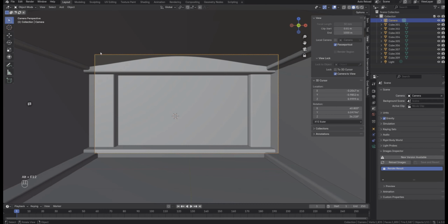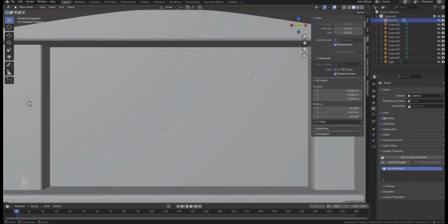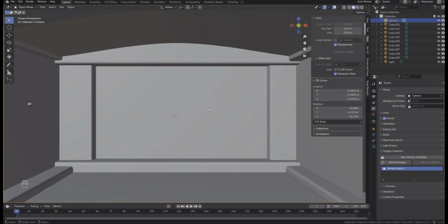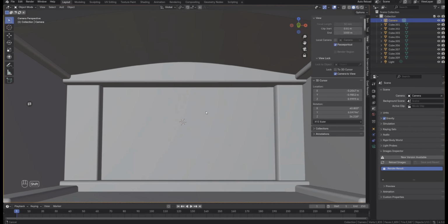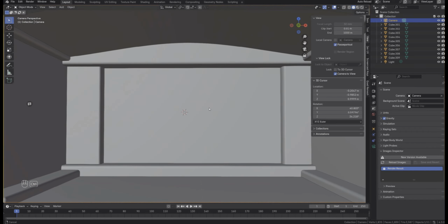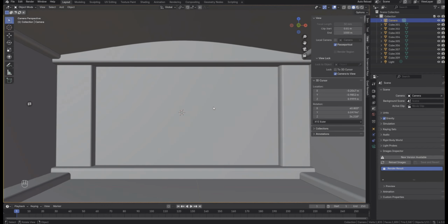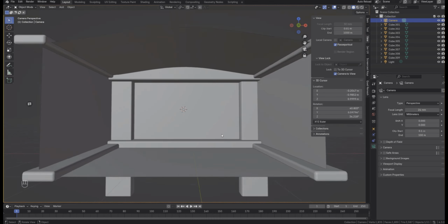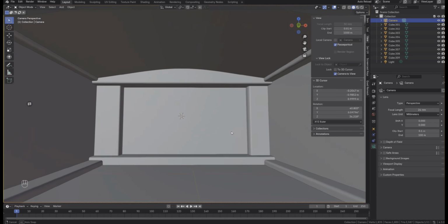You can see the part where we see the room is pretty tiny, that camera gate. So if I press Home, it will bring this camera gate to the full screen. Then I rotate my middle mouse wheel, press Shift to position this camera in the best possible way. I think I want to change my camera settings. So click here on the little camera, and I want to change the focal length to something a bit more dramatic, like 24. That gives us a bit more breathing room. We can even go 18.